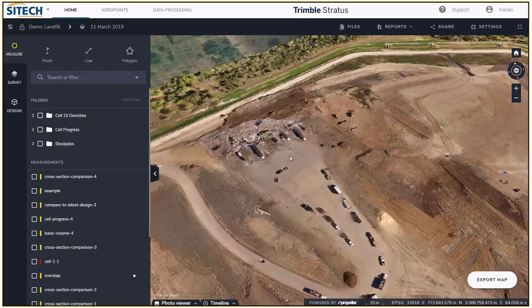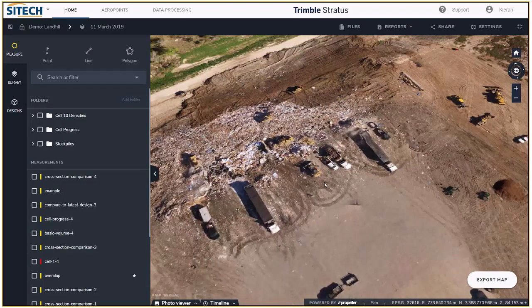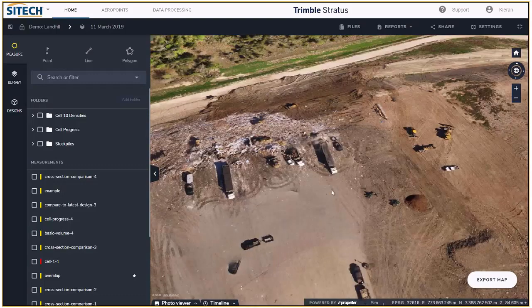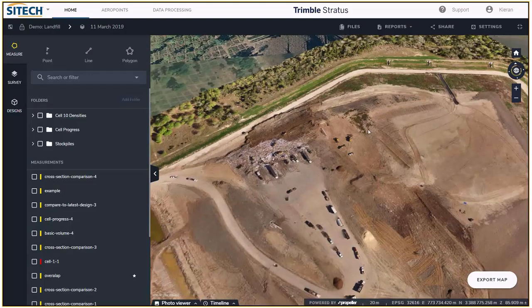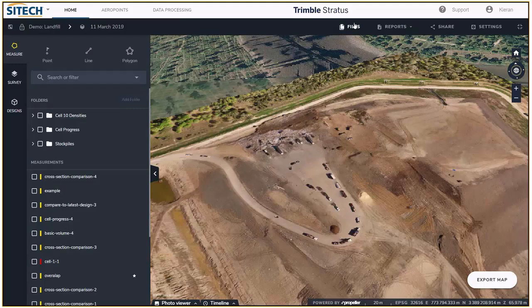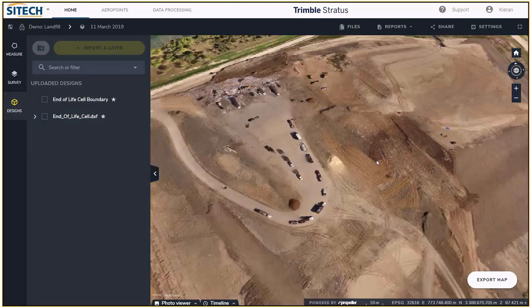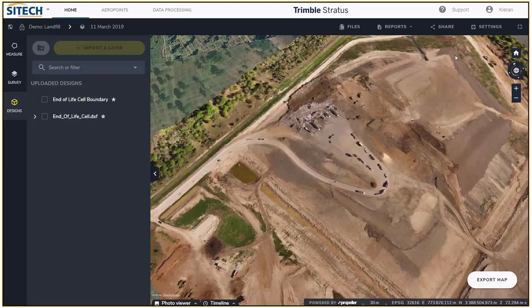So we're actually tracking a surface that it's creating. Essentially, if you think of a bulldozer or a compactor, if the base of its wheels, tracks, whatever is somewhere, that's where the surface is. So we're using GPS primarily, systems on the top of that, to say, right, well, I can know where that's been. I know what that surface is. I can pull that data down. I can pull the drone data down into TBC, combine the two together, and then re-upload that as an updated design, which isn't a design as such, it's more just the drone data where that is the latest and greatest.